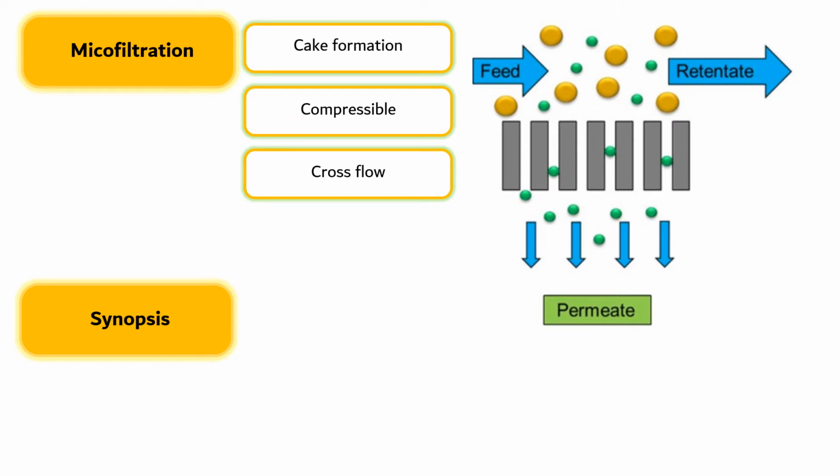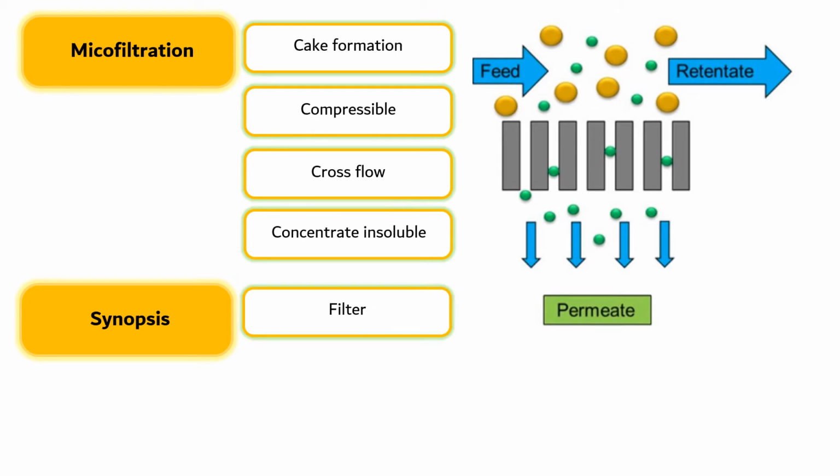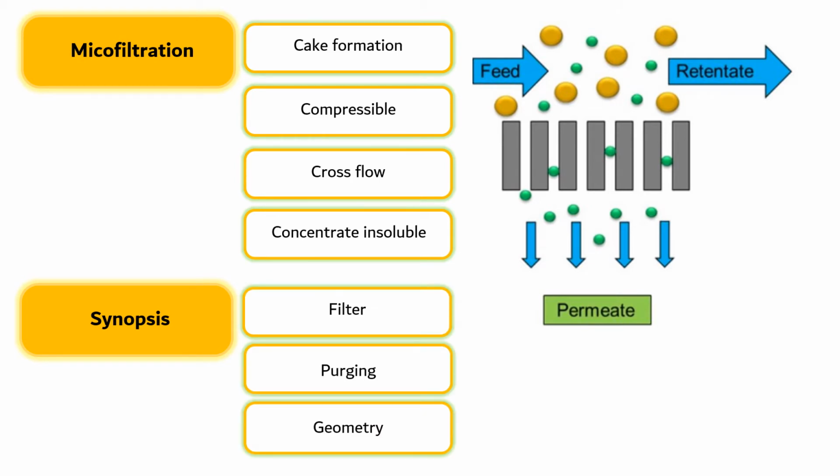Microfiltration is used to concentrate insolubles. It is like ultrafiltration and is analyzed with similar equations, which will be discussed in detail in Module 11. In this segment, we will briefly explain the filter itself, requirements for purging, and filter geometry to highlight comparison with conventional filtration.